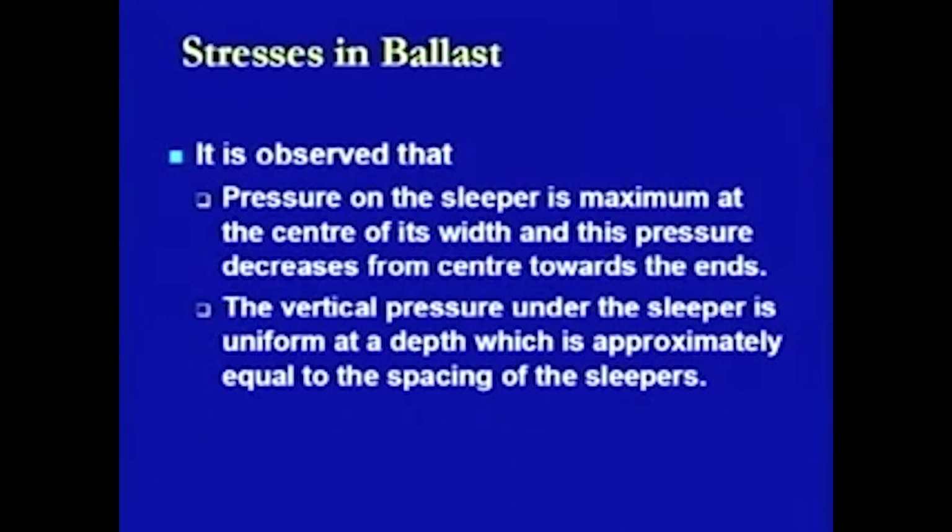So, if we go up to that particular depth, then we have to find out the total amount of stresses remaining at that level, and whether those stresses are lesser than the bearing capacity of the subgrade soil or the formation provided at the bottom. If it is so, then it is fine. If it is not so, then the depth of the ballast cushion is to be increased.